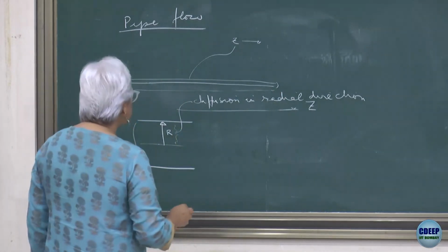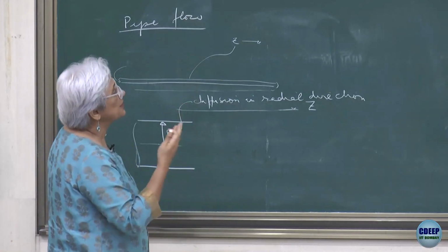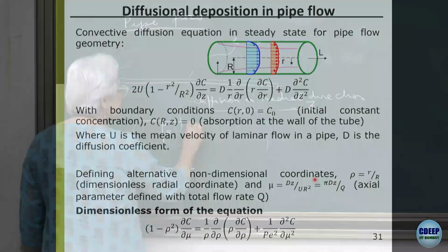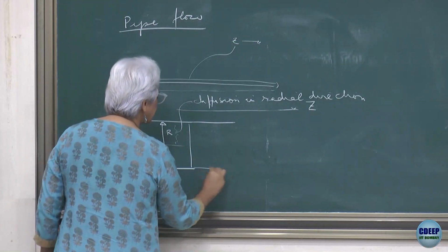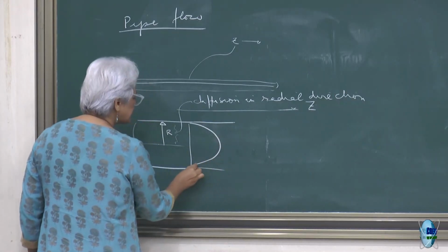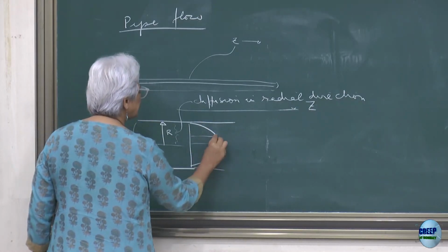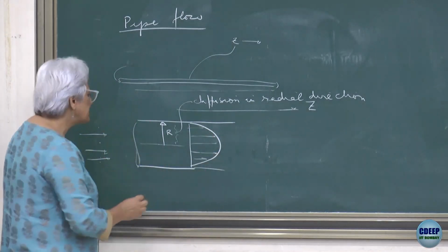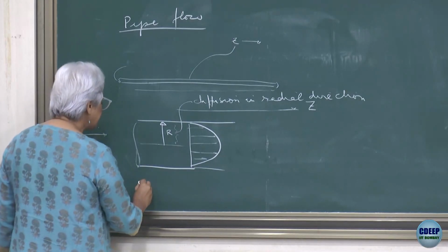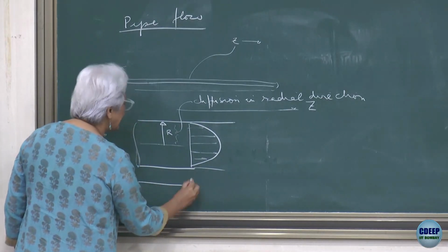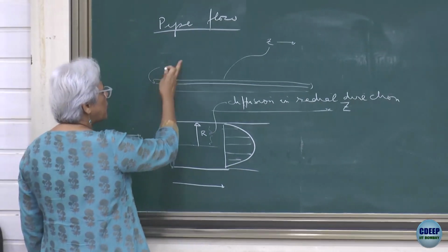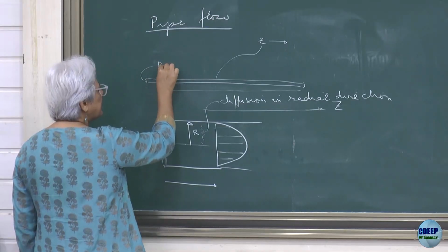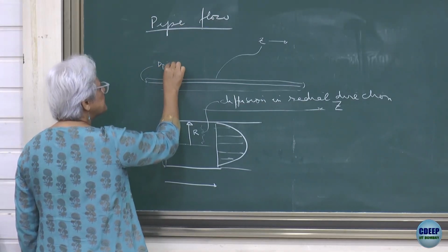And over here what is being shown, of course, is that you can have both laminar as well as turbulent flow. For the laminar flow case, we have this laminar velocity profile, and we will write the equation in terms of that. And notice this is a very small diameter, so you have the diameter of the pipe and the radius of the pipe.